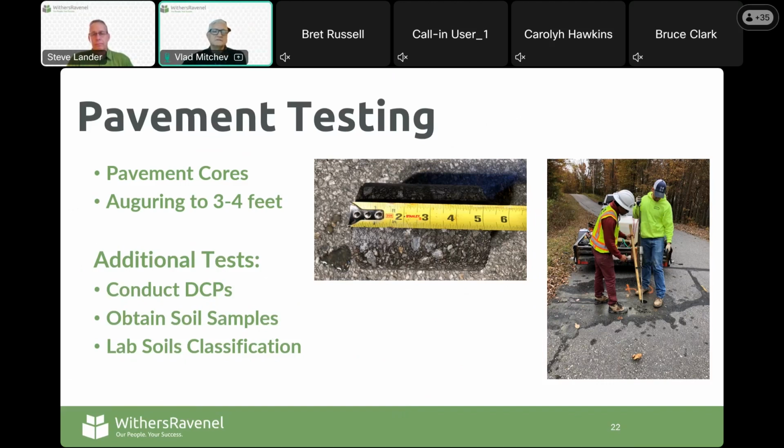You can also conduct CBR laboratory tests, which, if you do the in situ DCP CBR, is probably not needed, but it's additional information. Typically, in the existing section, the field in situ CBR value will be adequate for most resurfacing projects. If it's a new location, it is recommended to have a lab tested CBR value, which is with soaked CBR, soaked soil.